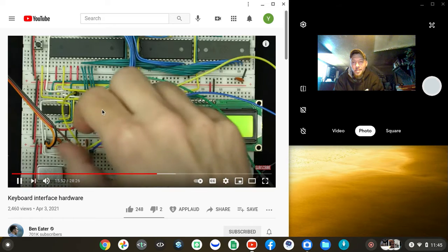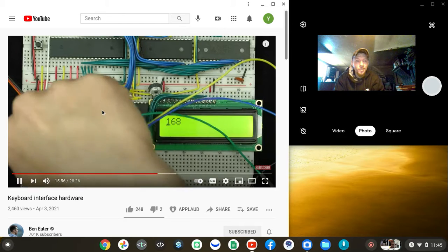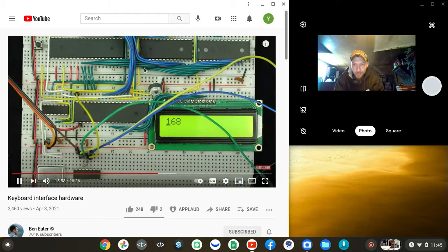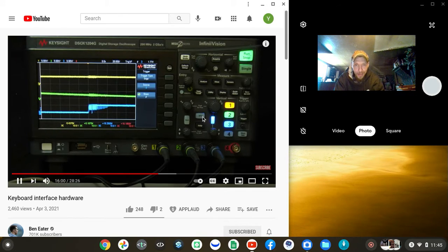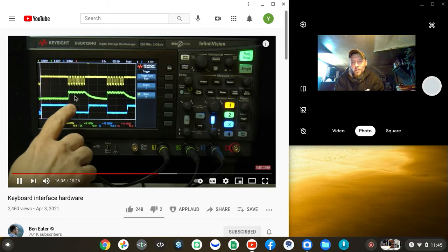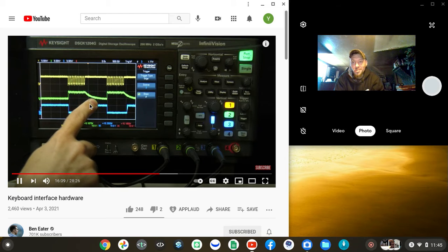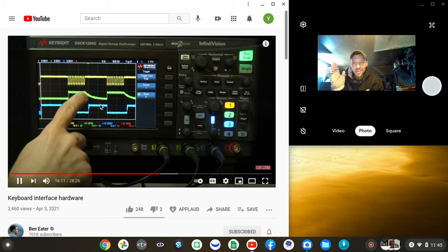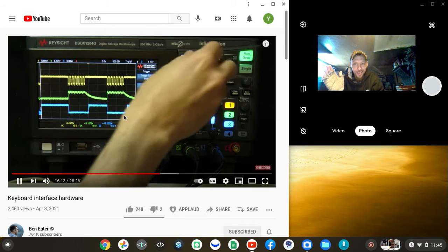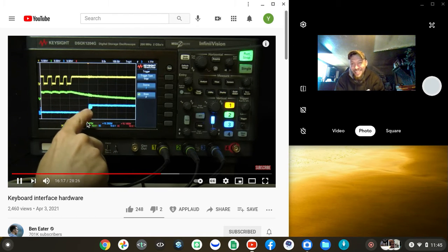Let's look back at the original analog signal feeding in. If we zoom out a bit here, you can see what's going on here. What I think is happening is as this green signal is discharging from the capacitor, we're passing through an area here where it really isn't either high or low. And it's kind of right at this area here where we're getting that ambiguous signal.